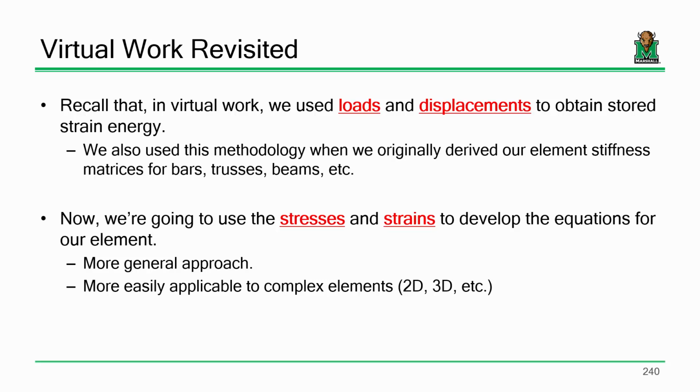So let's go back to that energy principle stuff. When we did all of that discussion regarding virtual work and the energy going into the system having to equal the energy coming out, we did it on a load and displacement. We did it from that perspective: here's the force, load it, what's the displacement? That's nice, but you all have had mechanics of materials, and you should know by now that if we're trying to develop a more generalized approach to discussing these types of mechanics, it's probably more appropriate that we look at things from a stress and strain perspective and not a load and displacement perspective. We can get the same response, but we should probably do it a little more generally, okay?